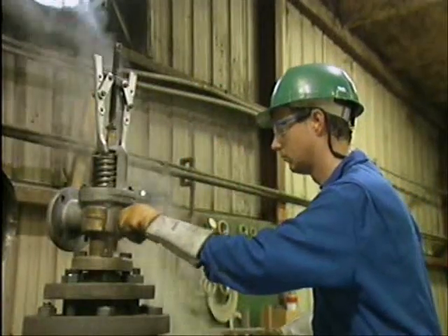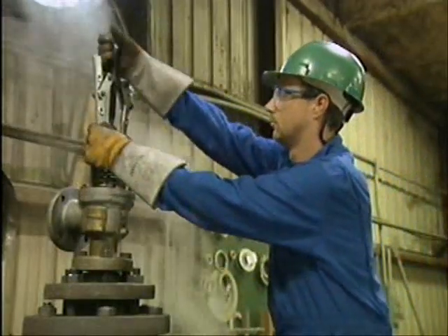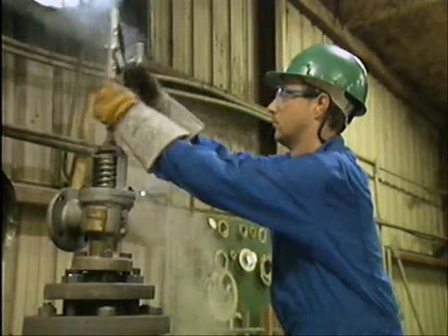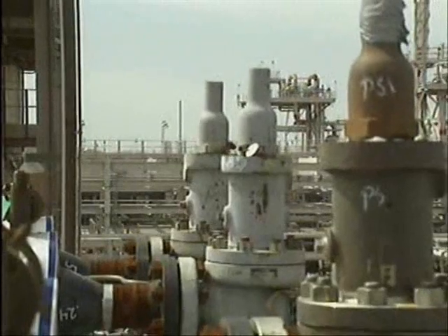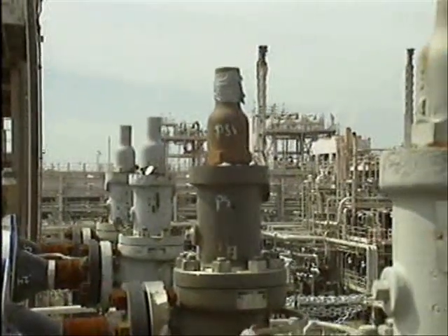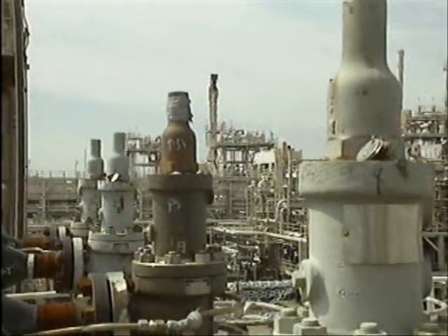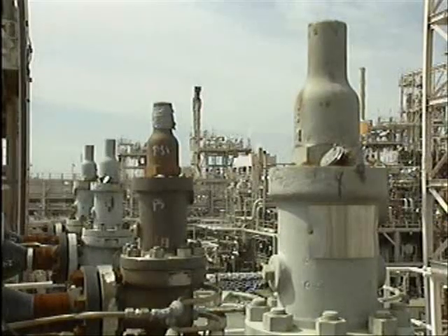Never leave a gag on a safety valve during normal system operation, because a gag makes a valve inoperative, and the system or equipment that the valve is installed on will be unprotected. Finally, many plant systems contain several safety valves. When you test the popping pressure of any of these valves, you must gag the valves that are set to open at a lower pressure than the valve that's being tested.